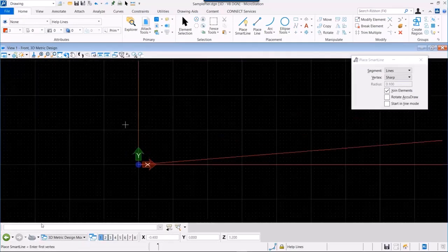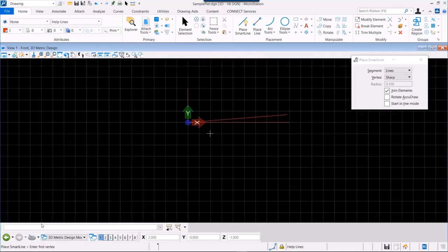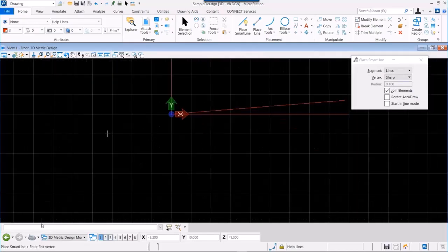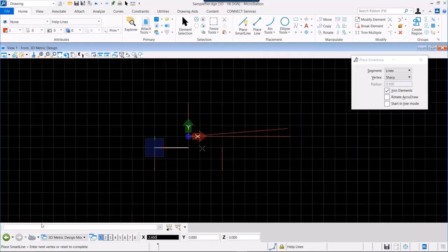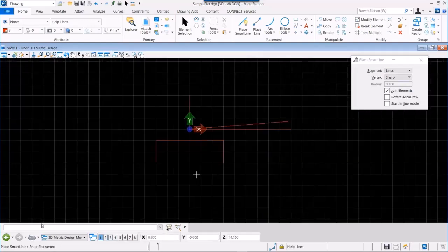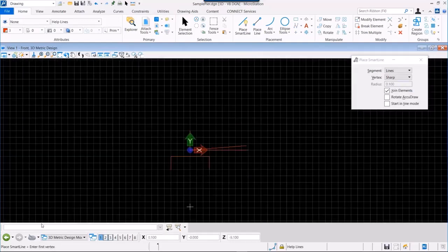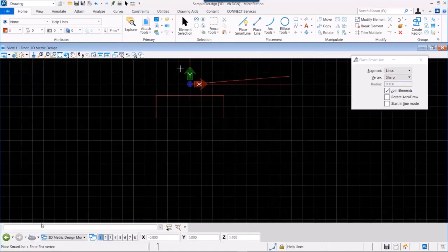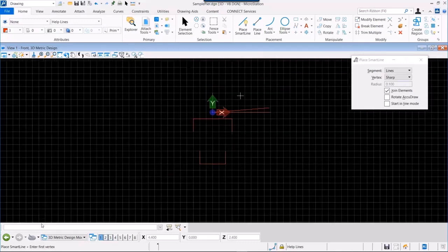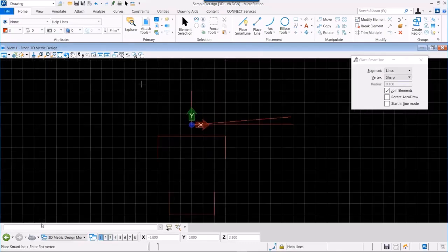There are many different ways, but one way that works for me is to define what we call help lines. So a coordinate system, for example if that inclined line is going to rotate, because my pier will accommodate superelevation. The first three lines there are the center lines and vertical dimensions of the cap, then also the footing, and the connectivity that the cap will have with the columns.